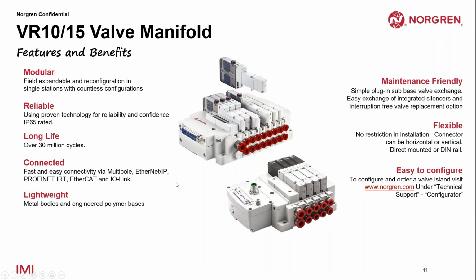So some of the features and benefits of the VR. The VR manifold is extremely modular and flexible, as mentioned. It's field expandable. You can build the manifold in single stations and even change a layout in the field. There's no restrictions on installation. The connectors can be horizontal or vertical. You can direct mount it or put it on DIN rail.